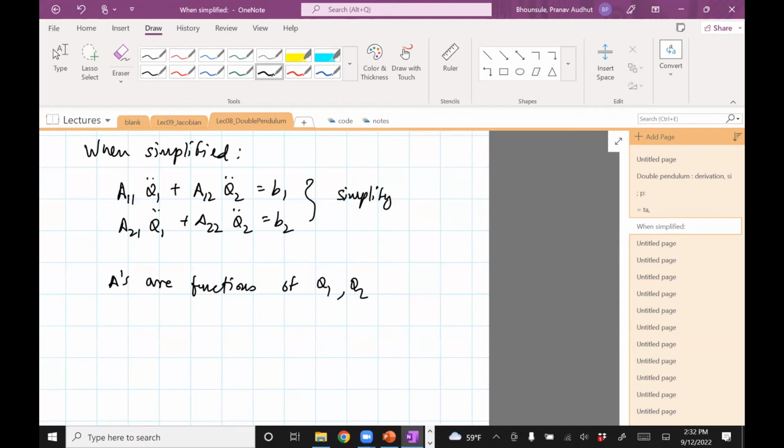And of course, the masses and so on, but the system degrees of freedom will only be a function of the angles, would not be a function of velocity. It's kind of important later on when we do control. These, on the other hand, are functions of theta 1, theta 2, theta 1 dot, theta 2 dot. So the velocities will appear in those equations.